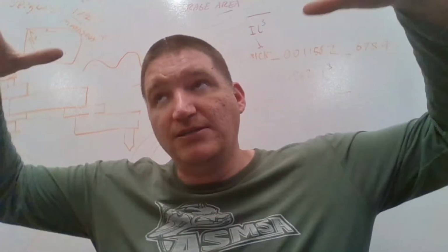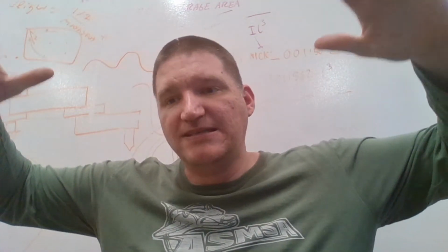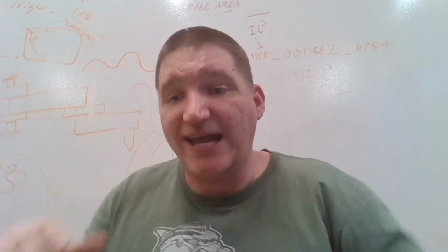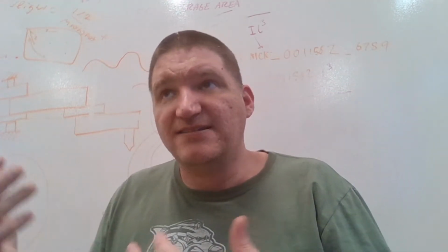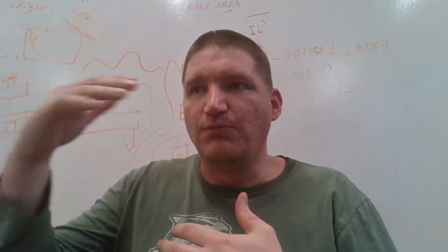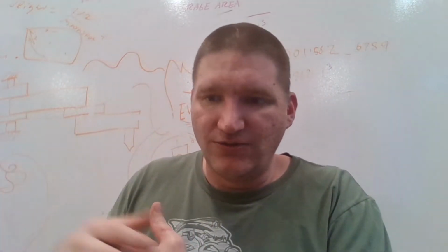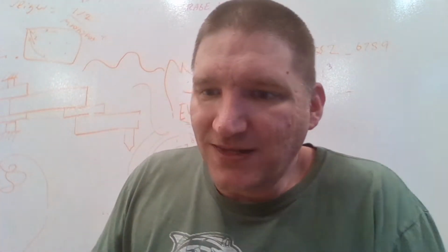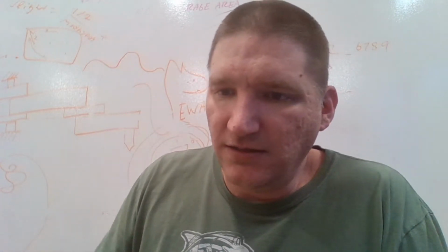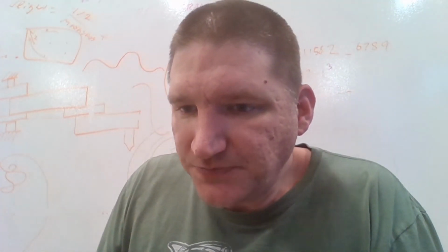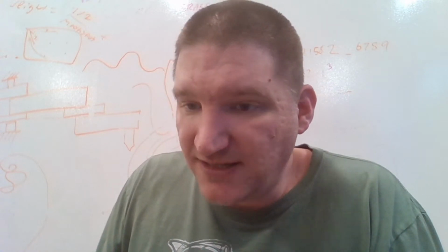Right now I'm doing a tilt down 30 degrees for the top ones, and then obviously the Z is flat. I like 30 because it has nice trig: the components are either a half or square root of 3 over 2. That will make all the math on the firmware side pretty easy. It's not as complex as it looks.